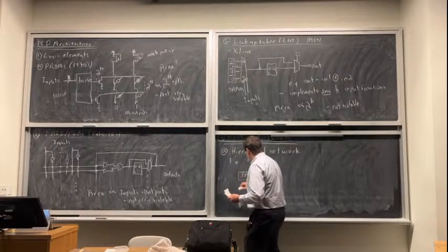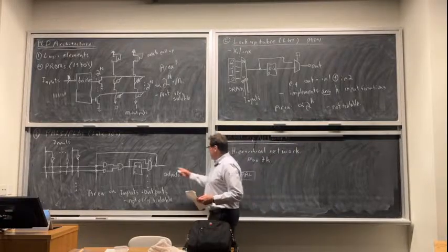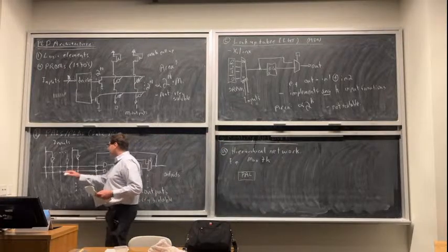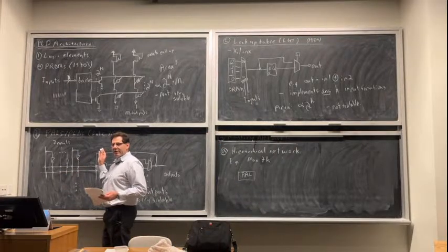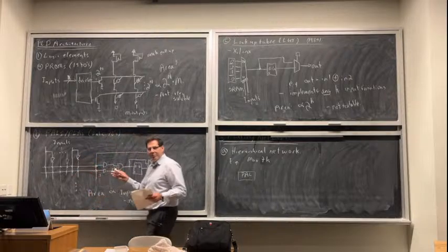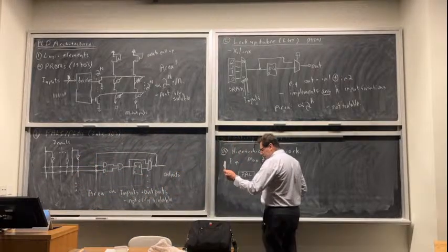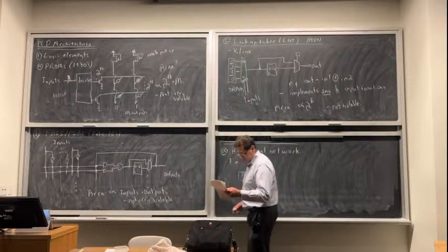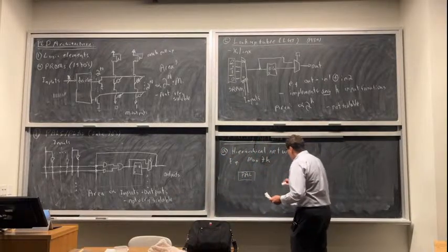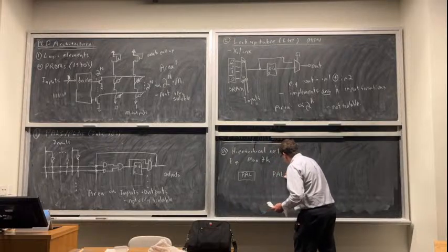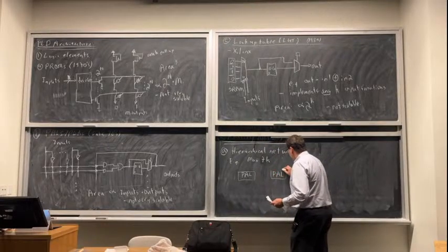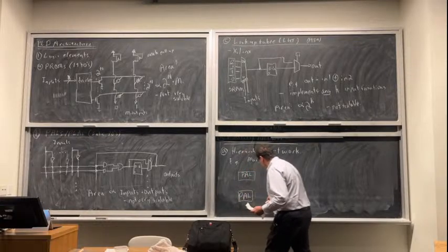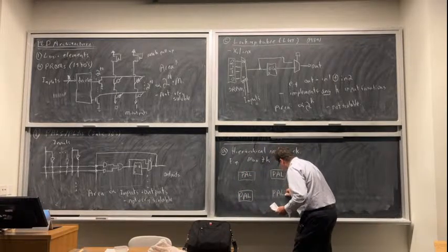Okay, so they basically make this structure, right? This AND/OR structure, and this scales up to some reasonable number, maybe 32 inputs and 32 outputs. It'll scale up to a reasonably high number of inputs and outputs. But beyond that, this quadratic growth starts getting you. So to make a bigger programmable logic device like that, they basically just said, okay, we can't make the inputs and outputs much bigger. It's too costly.